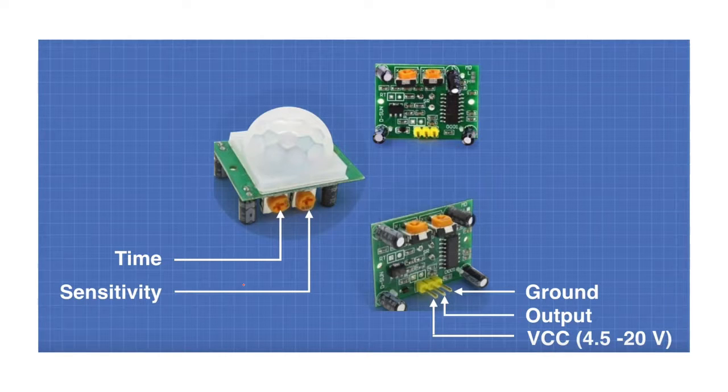But if it only finds movement and stops at saying there was movement, then even 5 minutes later you can still think there's movement, yet there has not been any. So you have to ensure the number of times you want it to check, the quality of timing, so that it keeps checking whether there is still movement in that particular space. Remember, it is a movement sensor, and it uses IR or infrared, which is beamed and moves out.